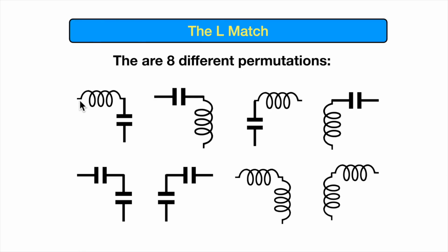Because if you've got an inductor as your series component and then you've got this shunt to ground with a capacitor, and if you think about what we talked about in the last video about the way reactance works in inductors and capacitors, and we talked about inductors being used as RF chokes to choke off high frequency. This functions as a low pass filter, because this will attenuate high frequencies but will pass low frequencies, and the capacitor will let the high frequencies go to ground.